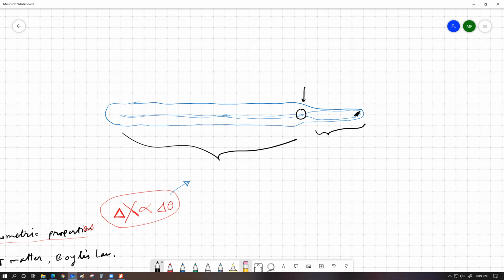And this is the stem. This is made up of thick glass, so it's not supposed to break, whereas the bulb is made up of thin glass walls so that heat exchange can be made easily. So that heat can enter into this or go out of this pretty easily, so that the thermometer can give us the reading pretty fast, because if we used thick walls then it would take a significantly long time for the thermometer to respond. Anyway, this is how the thermometer works.